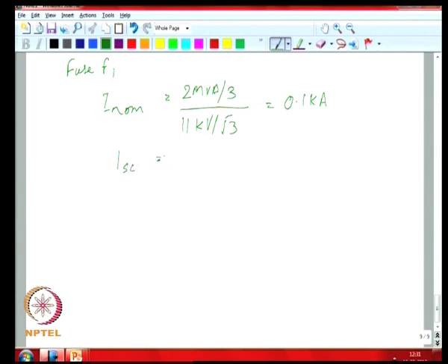And your short circuit current from your previous calculation is 6.3 kiloamps RMS or 9 kiloamp peak. So, that gives you two of the quantities that you would need for actually selecting the fuse. You know that your nominal operation is 11 kV, your isolation voltage has to be much larger than that.